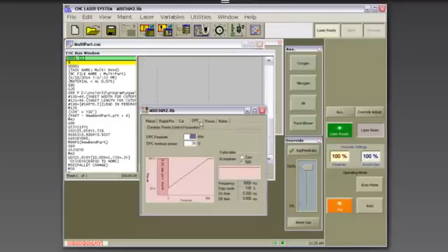If I go to my dynamic power control, a little bit about dynamic power control. We set up our DPC feed rate. It's currently set to 500 inches per minute. So essentially between 500 and 2,015 inches per minute, we're going to be cutting full power. And if you get into decelerating into a corner, or you have to cut features or holes less than material thickness, you have to slow down.